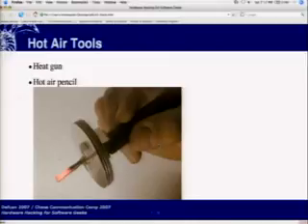Another type of hot air gun is for a completely different purpose, but they've got these wire sleeves that shrink around connections, if you're putting sleeves to attach a wire to a pin. You don't actually need a hot air gun for those. You can just take a big lighter and shrink it to the wire that way without spending $90 on an overpowered hairdryer.